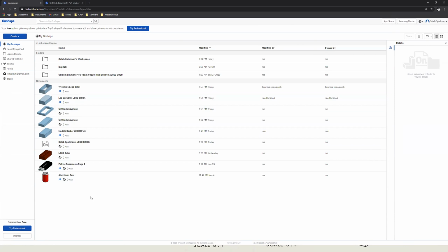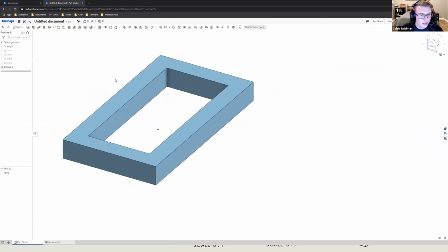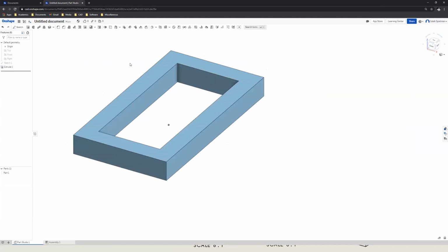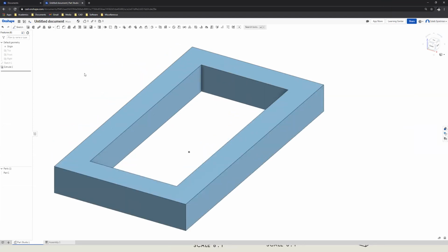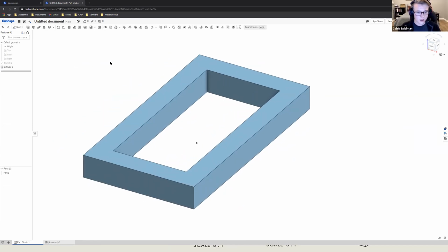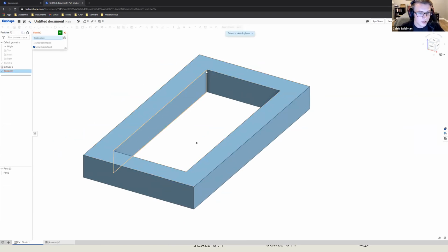So somebody is watching my chat. How far should I extrude the inner rectangle, the inner contour? The inner rectangle? Do you mean like this, or the lid piece? You see how the middle has nothing in it? Yes, that part. All right. So what we're going to do is make a sketch, since we want this solid to start from the top of this one, depending on what dimension for the height we chose.